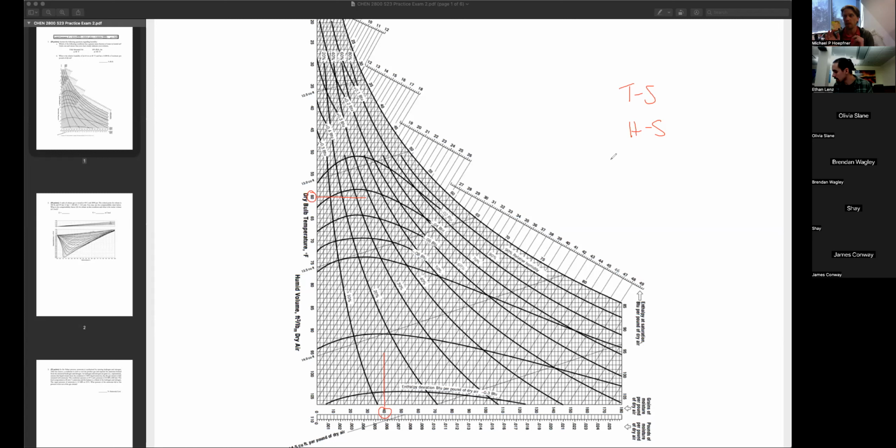So let's go to the wet bulb temperature, which you mentioned. We can see that the line is curved here. Coming out perpendicular to these curves, following the same idea, the lines go out perpendicularly to the actual measurement. So the 55 line is this one here. If I had 60 degree dry bulb and 55 degree wet bulb, that would put me at a relative humidity around 70%.